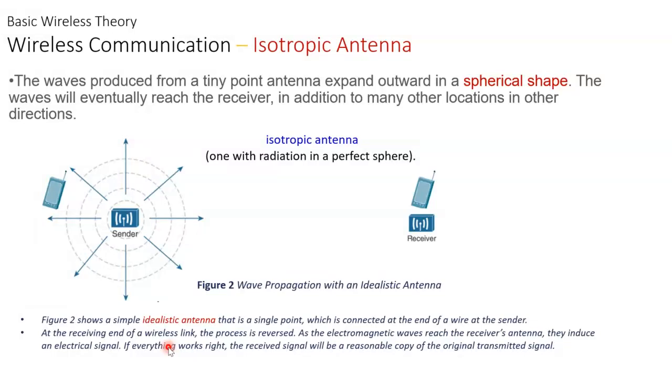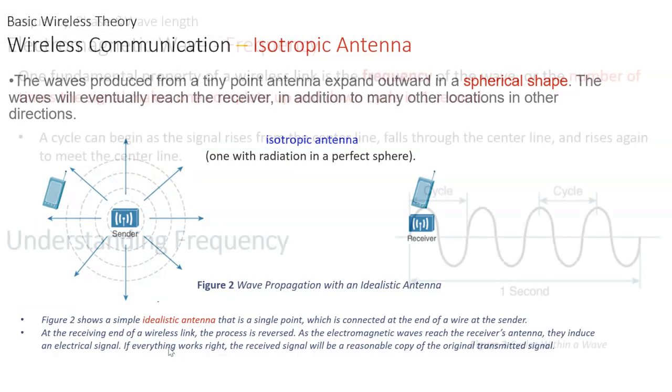And when we say that any antenna has a gain of 10 dBi or 20 dBi, it means this antenna has a gain of 10 or 20 with reference to this antenna. So this is a reference. This antenna, which is the isotropic, is used as a reference model for comparing the real antenna gains.